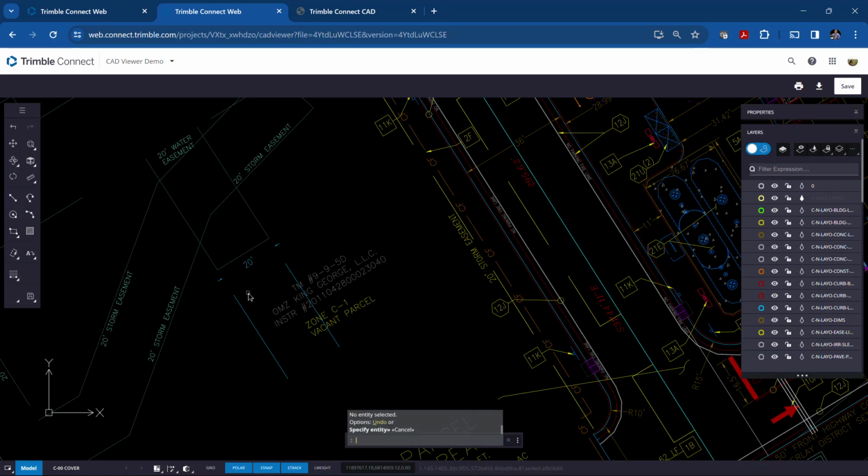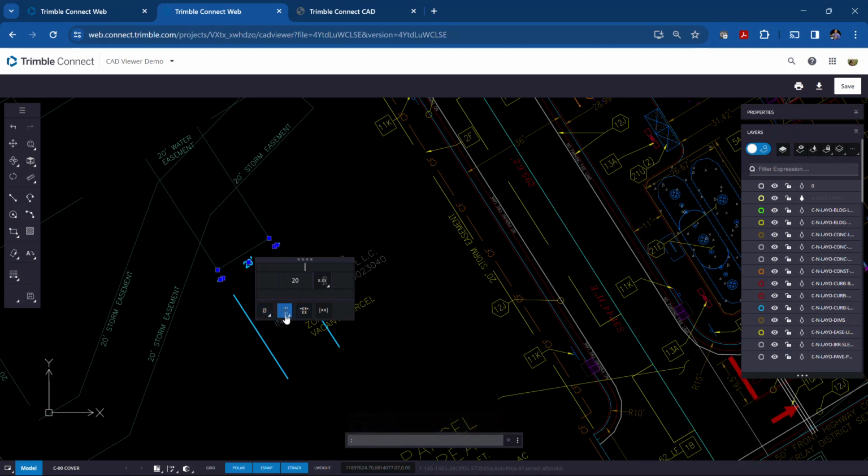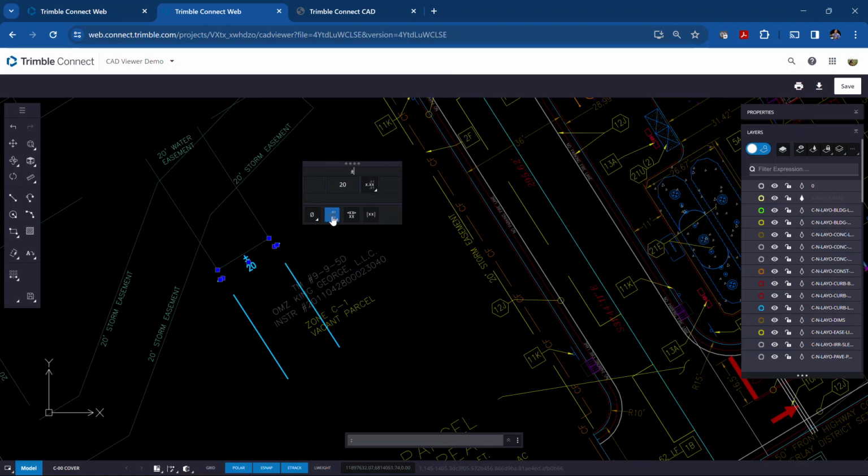If I escape, that's one object, and you've got this glyph where you can come in and change some of the settings. You can insert a symbol. There are different symbols, maybe plus minus. You can change the unit precision. So if we want it to be just one, move this out of the way, just 20. You can come in and override the dimension value. So I could do that. Obviously, you wouldn't want to, but you could.